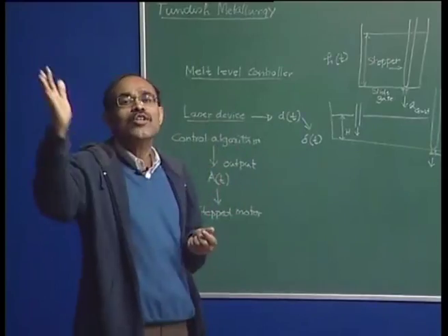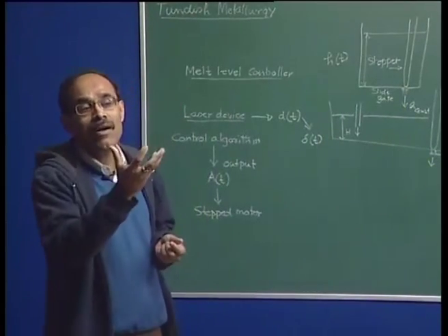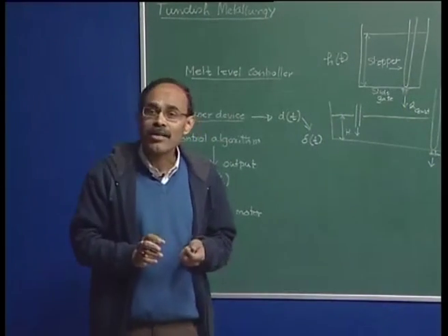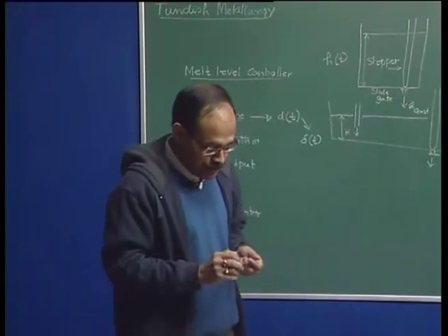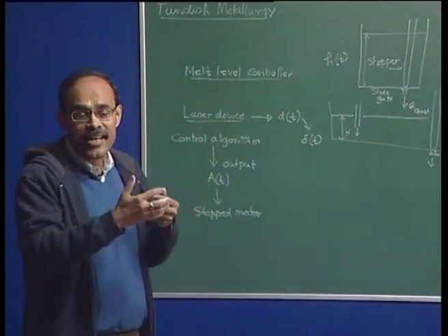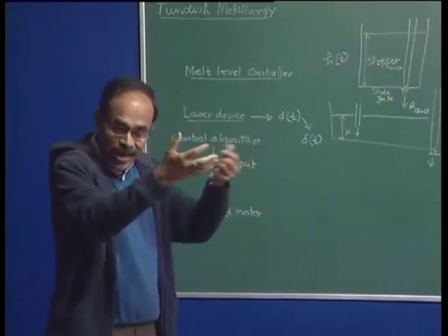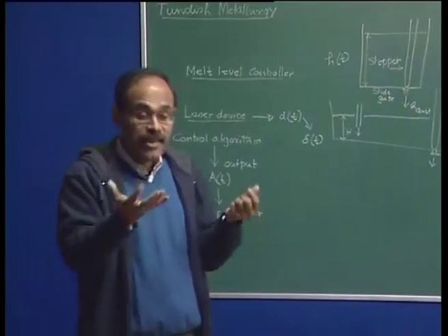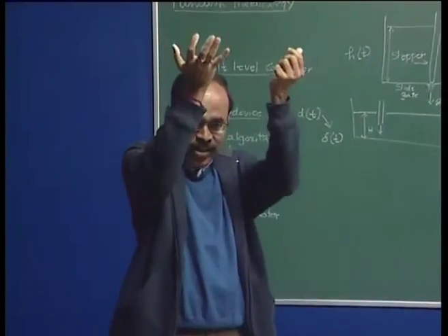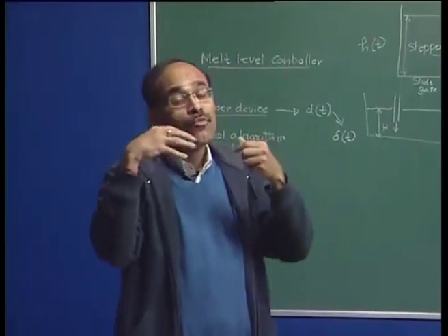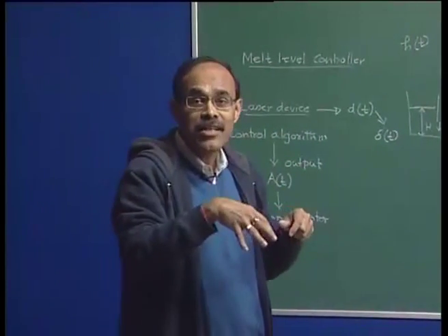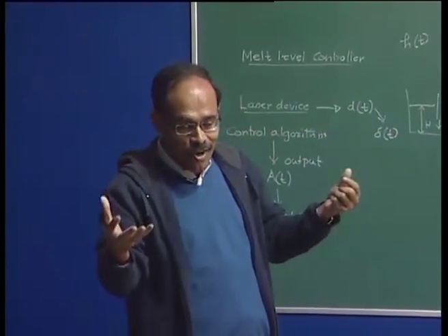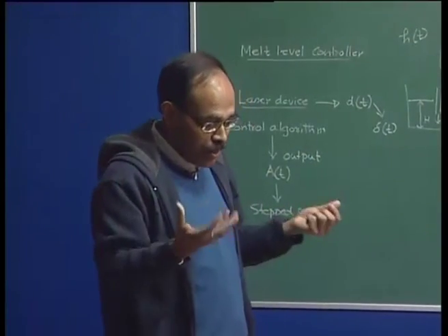All through the duration of secondary steel making we will have gases injected from the bottom, through either one or two porous plugs. Now, following inert gas stirring, we can go for arcing process, where we can increase the temperature, which is the ladle furnace, which increases the temperature of the bath. We can also do alloy addition and compensate for heat loss and alloying, etc., through the arcing.